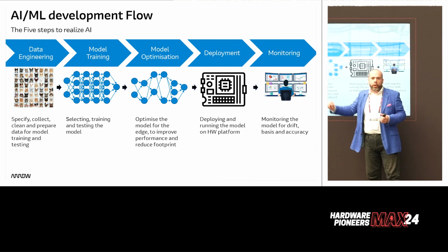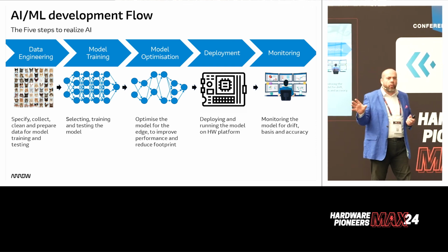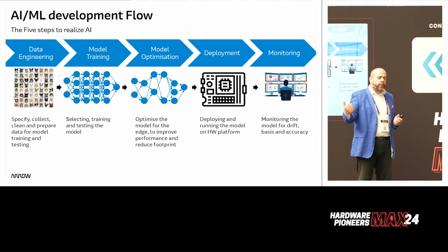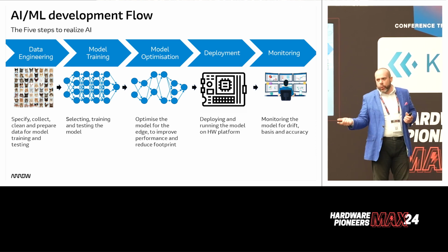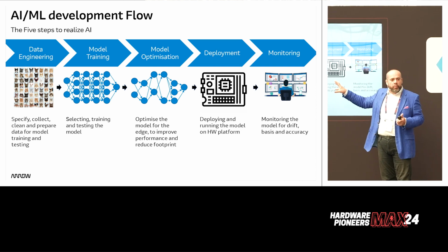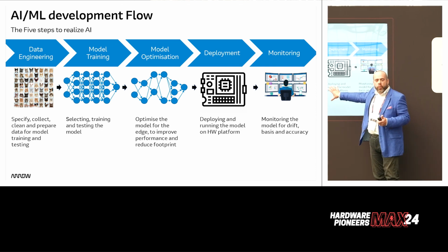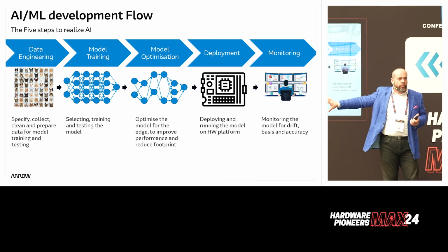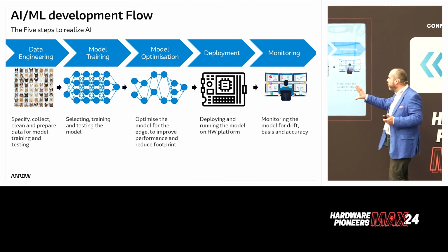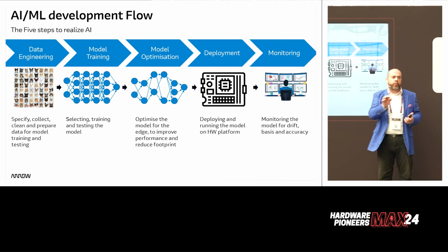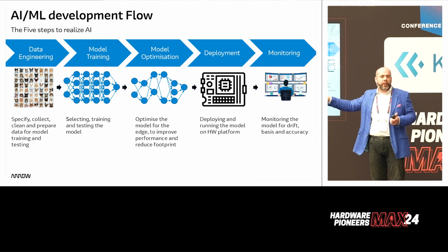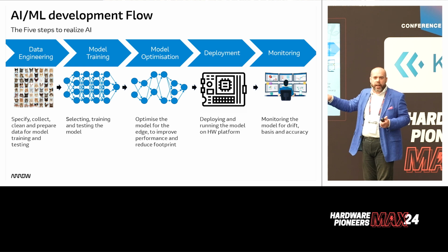So that's where we go to model optimization. Model optimization, primarily 2 or 3 techniques. We have quantization, pruning, and possibly transforming. Once you then have your smaller model, you then have to choose a hardware platform to deploy it on. And that's a whole area in itself that we can talk more about at a later time. But basically, it can be anything from the simplest microcontroller right the way through to specifically designed system on chips with AI accelerators and pipelines.